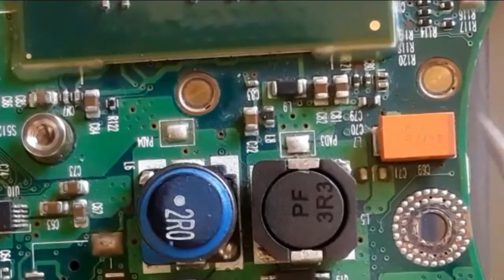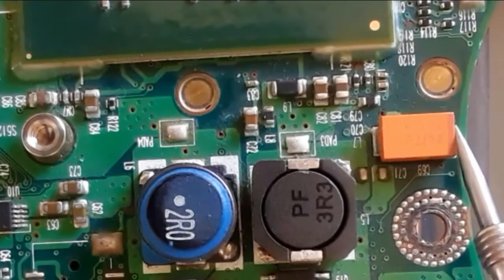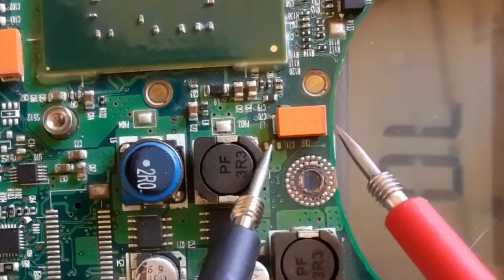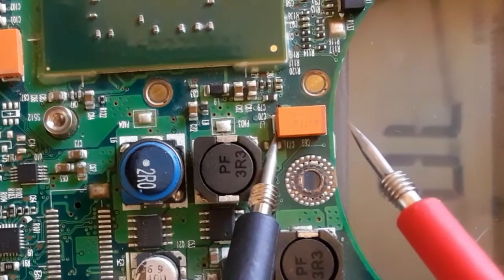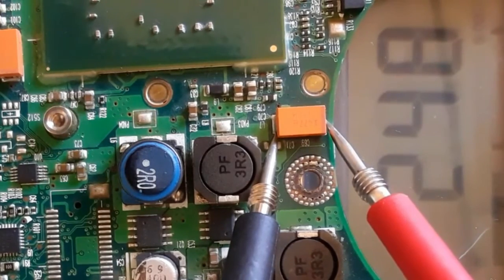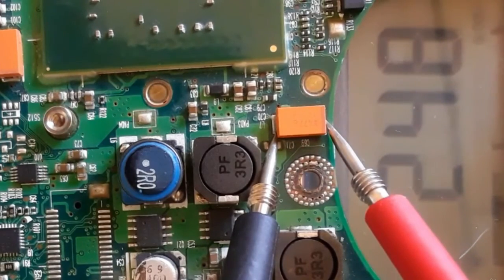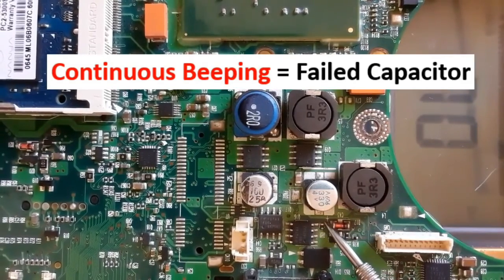Okay, so here we have a tantalum capacitor that we're going to check. To check this capacitor, basically we should determine the positive terminal. The band means positive terminal. So let's check. As you can see, we have a reading in the multimeter. The value increases and decreases, which means the capacitor charges and discharges, so this is a good capacitor. Okay, if you get continuity or a buzzer, it means the capacitor is bad.